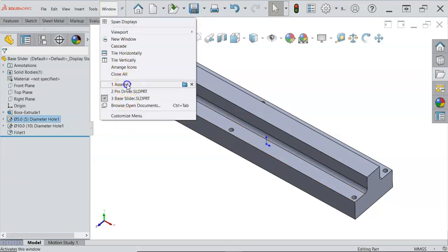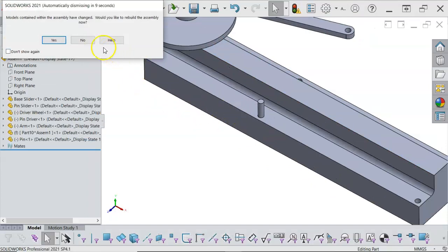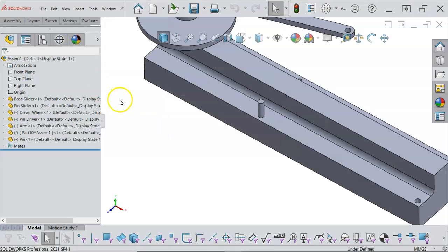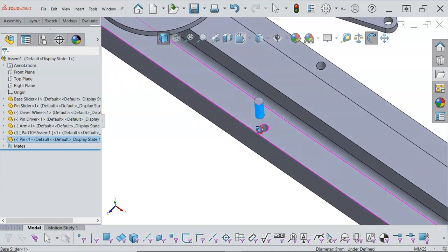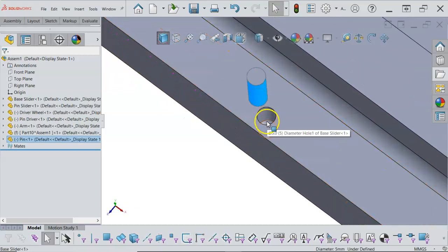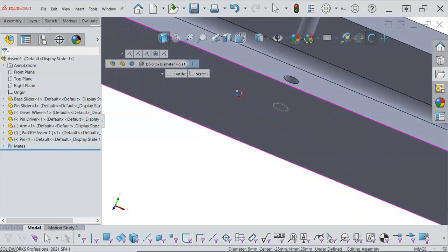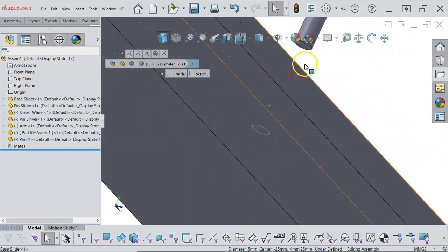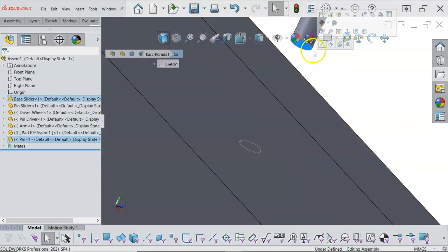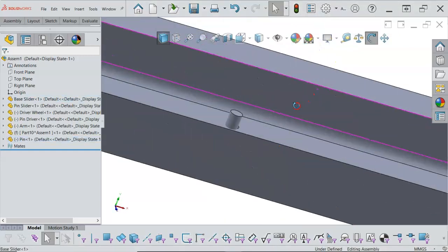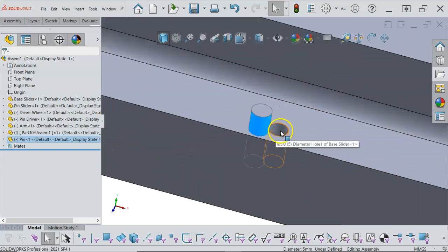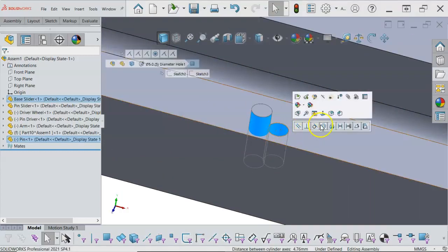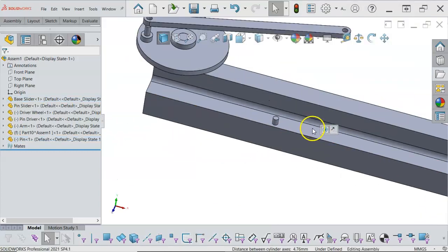All right, so the window back into the assembly. That looks a little closer to size, and you're going to find and do this error checking as you're going through the process. So this one can be kind of strange. If I want to tell it to go till it seats, then I will probably pick the edge and control select the face, and those can be coincident. It's still a little bit off, so we'll drag it out of the way and then make that concentric.